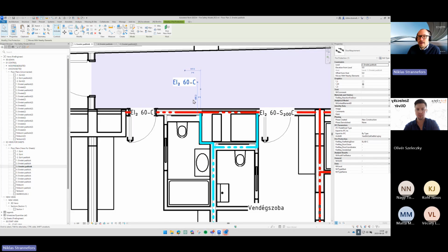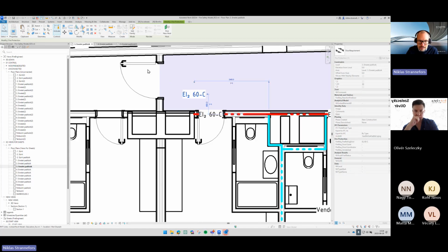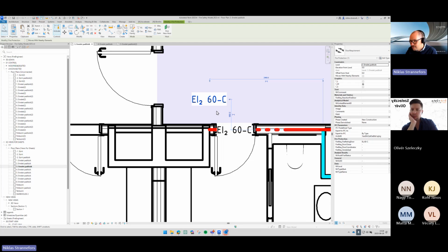What we do is we basically grab every symbol that is selected, because I went with selected, and go to its origin, which is the base point of the symbol, and we make a sphere, 200 millimeter in radius, and check, is there a door or window or wall there? And if there is, we connect. 200 millimeter is short because sometimes doors can be too close. We'd rather fail than automatically connect to the wrong door.